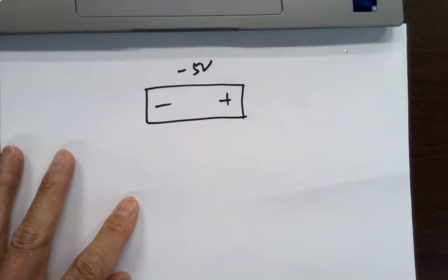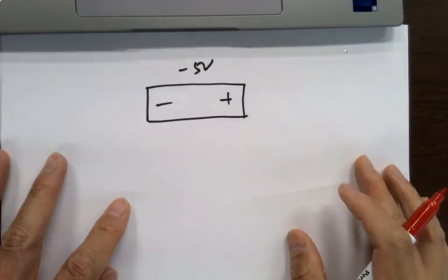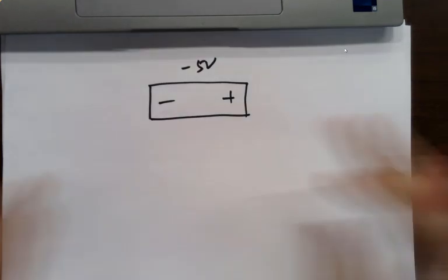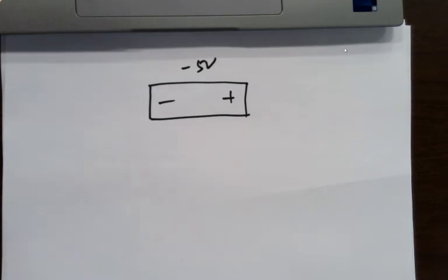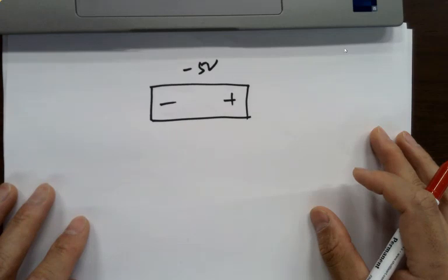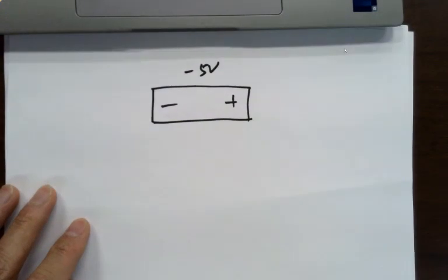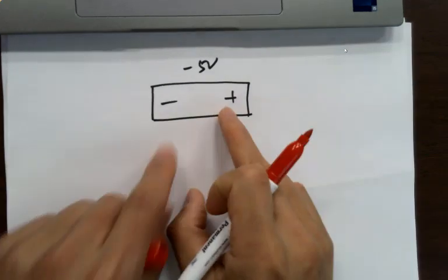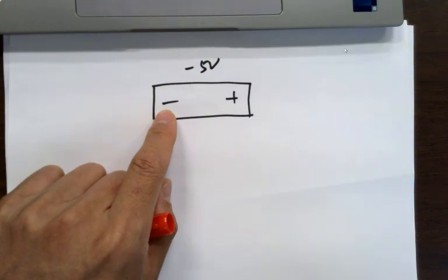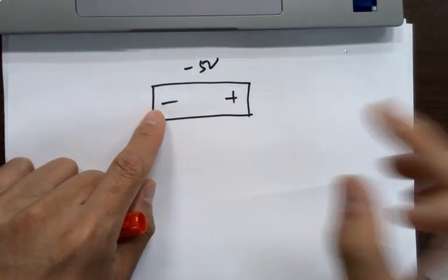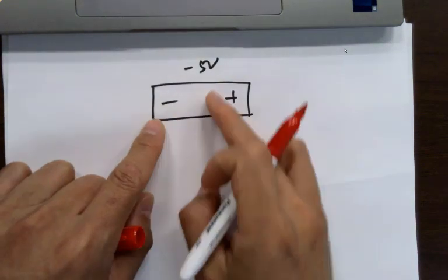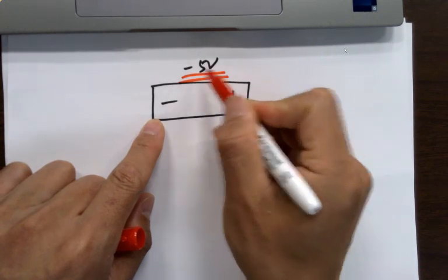I want everybody to catch it, not just people in the front. Do you get it? Or just keep it in mind. These problems will be repeated all across the first few weeks, so if you don't get it now, don't feel bad. Eventually you'll get it. It's super simple, just voltage and current polarities. If you play with it for a long time, you'll get it. Plus minus labeled that way doesn't mean physically in the circuit you are getting a positive voltage drop from here to here, because it could be minus 5 volts.